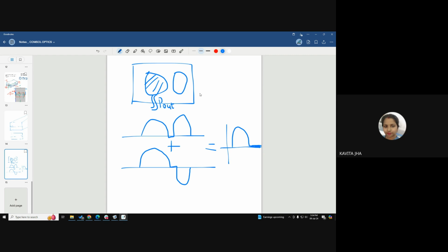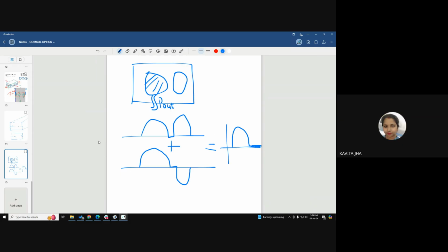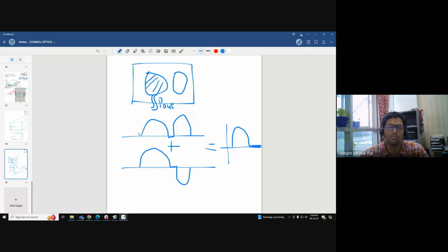Sir, in case of multimode propagation, can we use this integration technique to find out the modes? Yes, the same thing. If you see that equation, it is the integral of the power, and then I have integrated this. So, for example, this is the power of the first effective refractive index, right? Similar to this, there will be many others. If you see that plot that I was showing, now it is 10 effective refractive indices. It could be hundreds in your case, right?